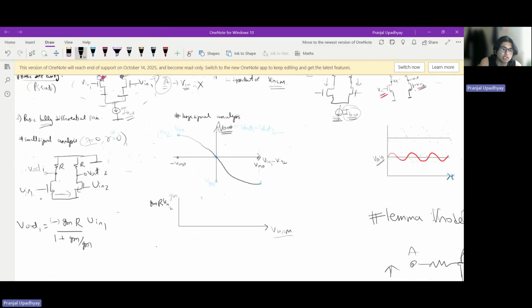And now I have to say what is the signal at the Vout1 terminal due to Vin2 when Vin1 is grounded, okay? So now if I'm applying Vin2 over here, what is basically happening in the small signal model, when this guy is shorted, is that first Vin2 will appear here through a source follower stage, right?